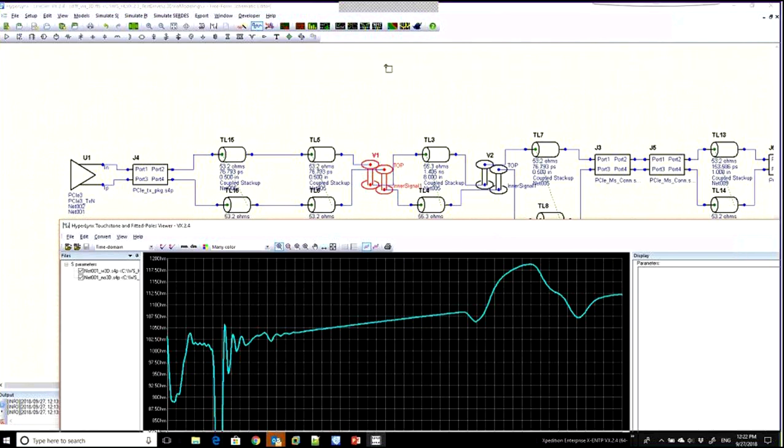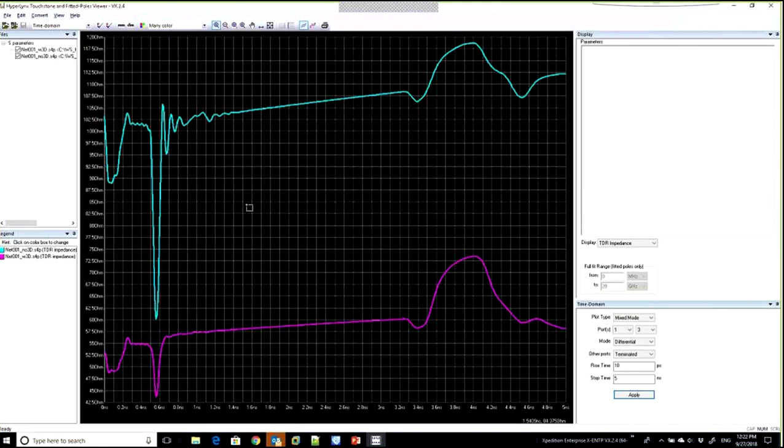Anyway, it's just a nice way to tell. So if before I looked at the S parameter model and said it's not as good, there's a problem, and I compare the two, I can plot it out here with the time domain response and see, as the waveform goes through from the driver to the receiver, where that issue was. And we can see that it's with the via. That's what that section of this is. It doesn't label this as via, but we can look, with some intelligence, at where in the topology that problem popped up. So I think that's pretty cool.